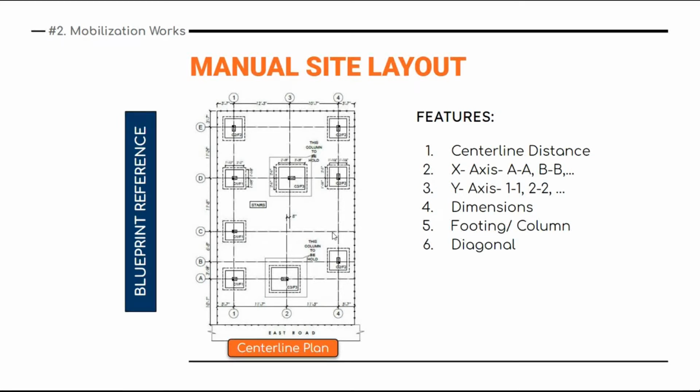So the dimensions are quite important. You can see here the dimensions have been given from the center line. How much distance is this, how much distance is this, these are all given in the center line plan. So these dimensions are quite important to understand. Then where the footings are placed, these features are also important.